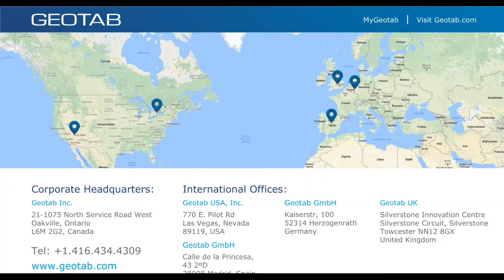The IOX analog can be used to record that value, and then the conversion from 0 to 30 volts to 0 to 100% fuel level is done in my Geotab through the reports. Other than that, that's it for the IOXs. You can always go to geotab.com, and under support and support documentation, we have a section for all the IOXs and harnesses provided by Geotab.